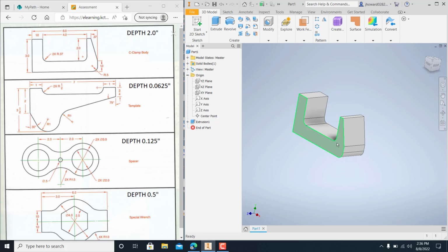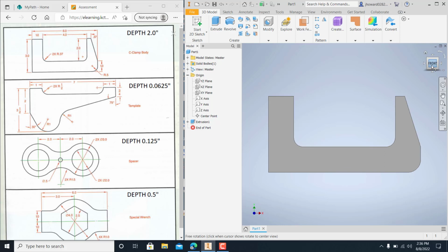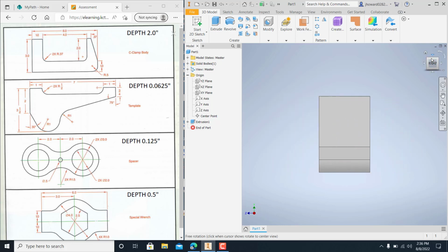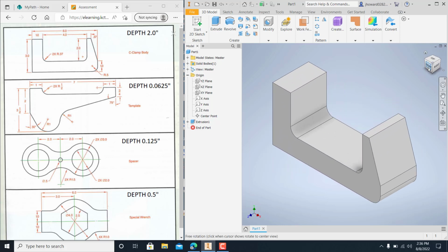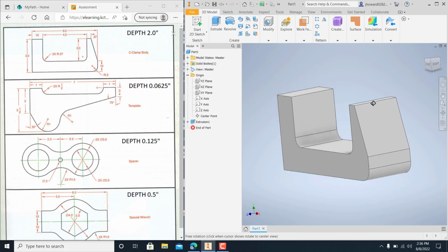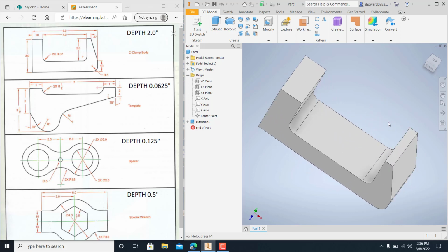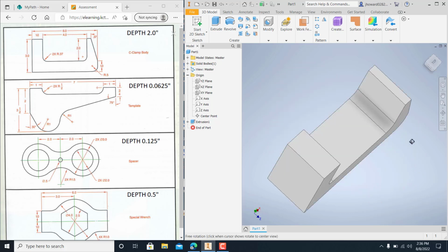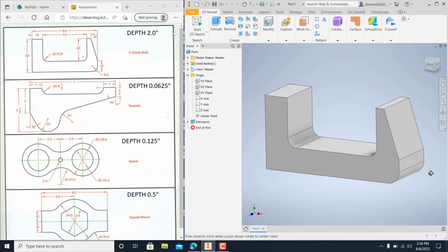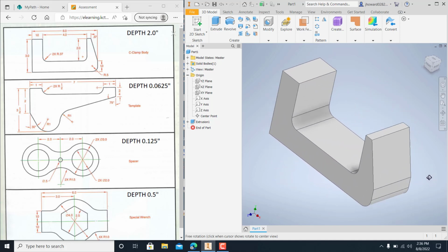And now you have yourself this C-clamp bracket. Now, you do have a view cube up here. You can actually click or turn. I want y'all just to toy around with that. That catches it isometric. But you also, if you hit Shift on your keyboard and hold it and smash your wheel down on your mouse, you can rotate it and pivot it around, okay?